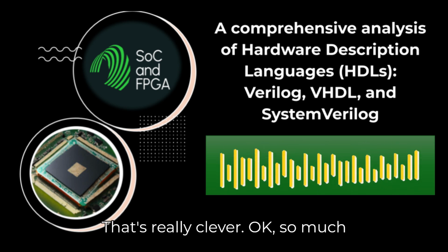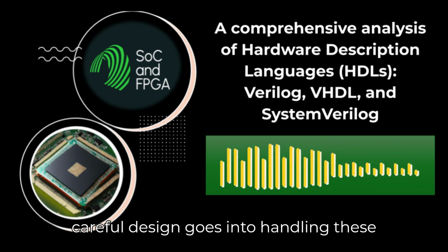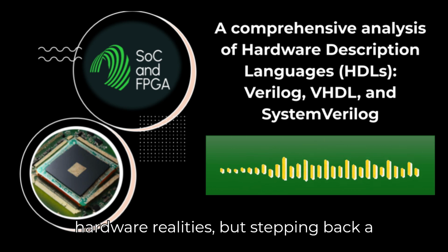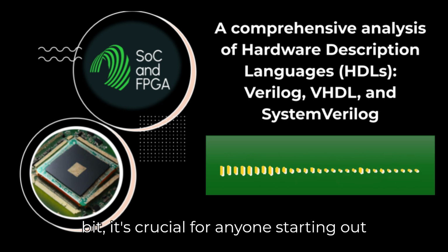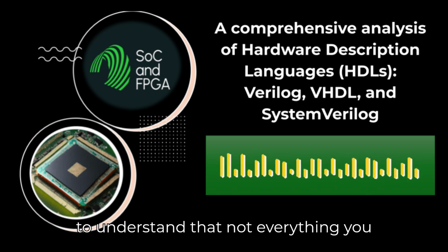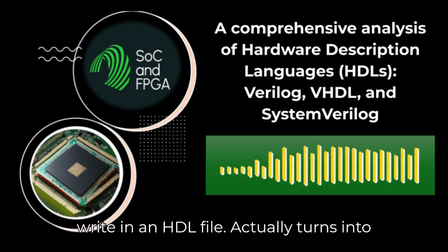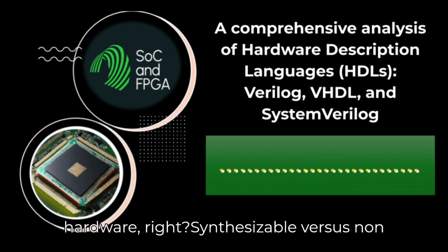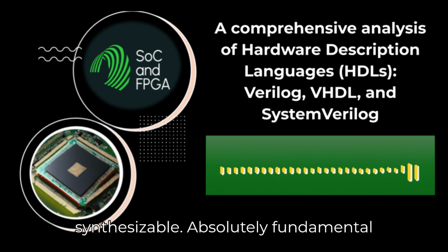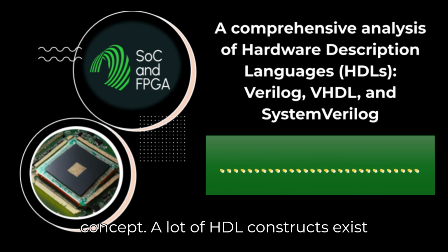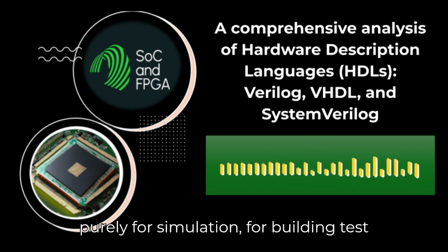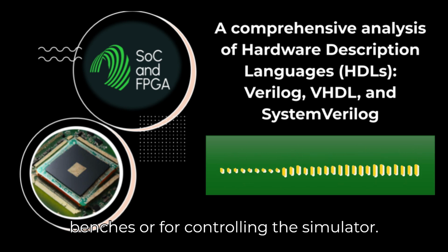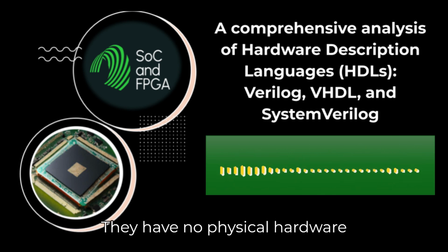That's really clever. Okay, so much careful design goes into handling these hardware realities, but stepping back a bit, it's crucial for anyone starting out to understand that not everything you write in an HDL file actually turns into hardware, right? Yep. Synthesizable versus non-synthesizable. Absolutely fundamental concept. A lot of HDL constructs exist purely for simulation, for building test benches, or for controlling the simulator. They have no physical hardware equivalent.